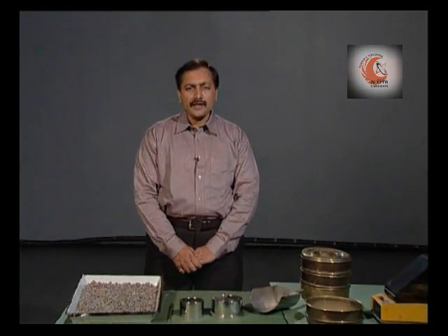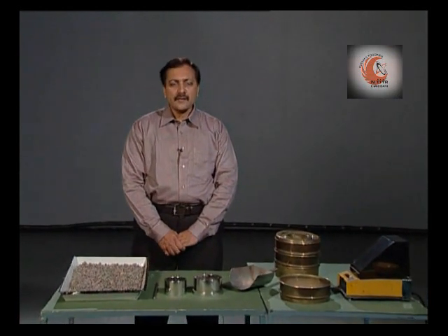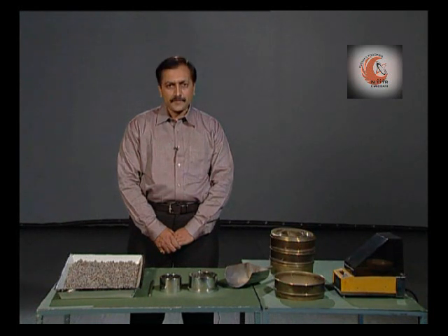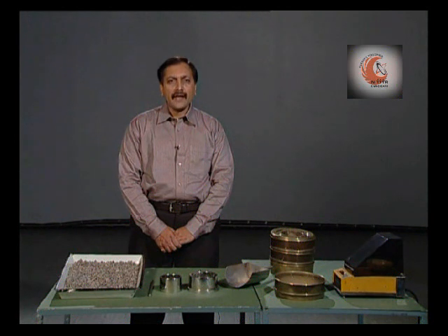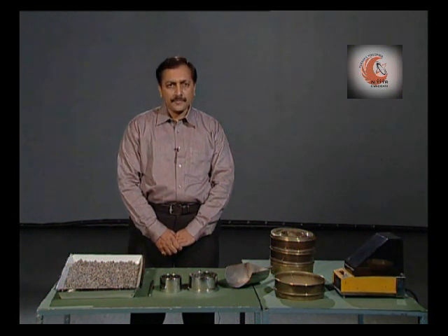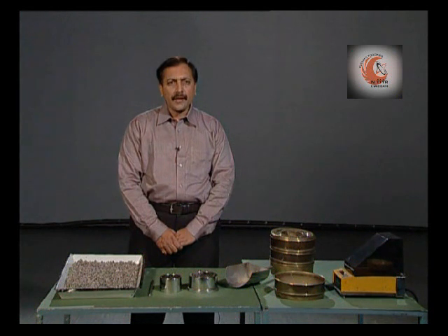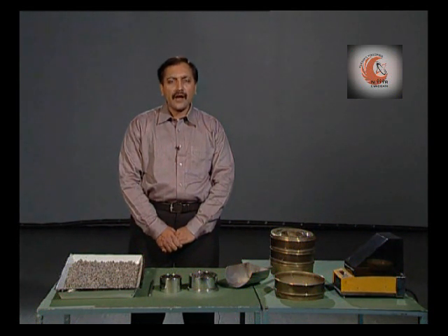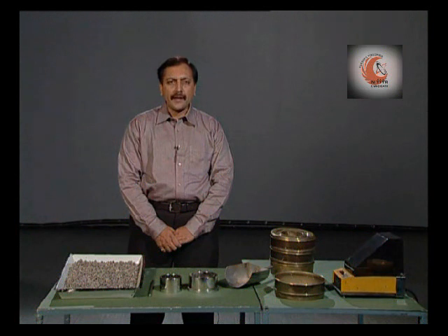As we know, aggregates are the prime constituents of different layers of road pavement. The aggregates are subject to bear the impact load caused by moving vehicles. The property to resist the impact load is termed as toughness. It is determined by aggregate impact value. In this program, we shall see how we determine aggregate impact value.